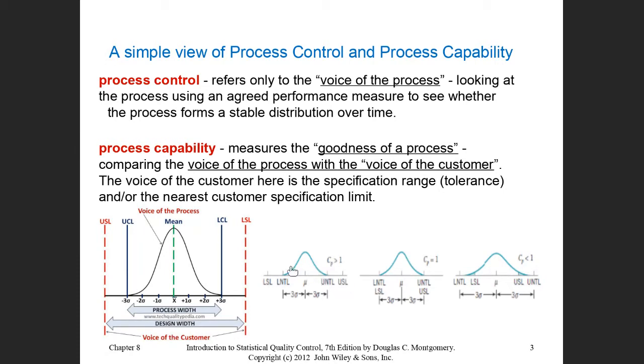So your regular or your ideal case is when you have your natural tolerance, which means the 3 standard deviations that are normal to have in the process, within the specification. That means it is narrower than the specification limits. So when you exceed your natural tolerance, you are not exceeding the specification limit.